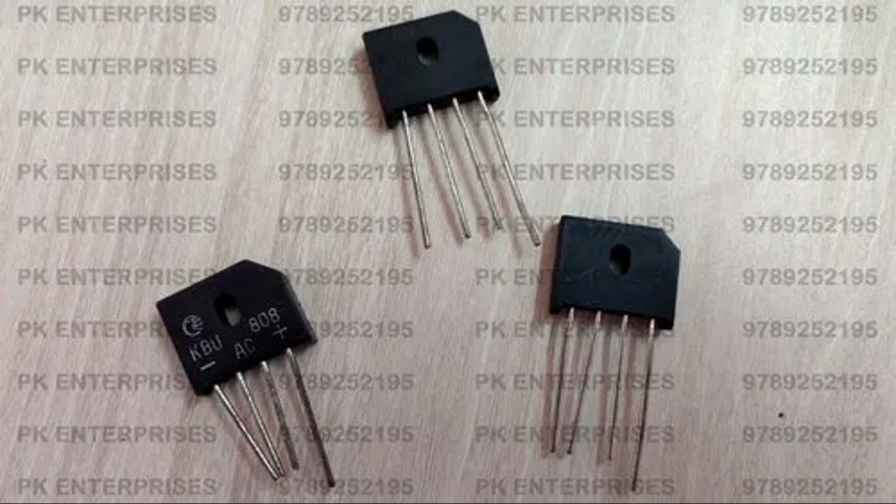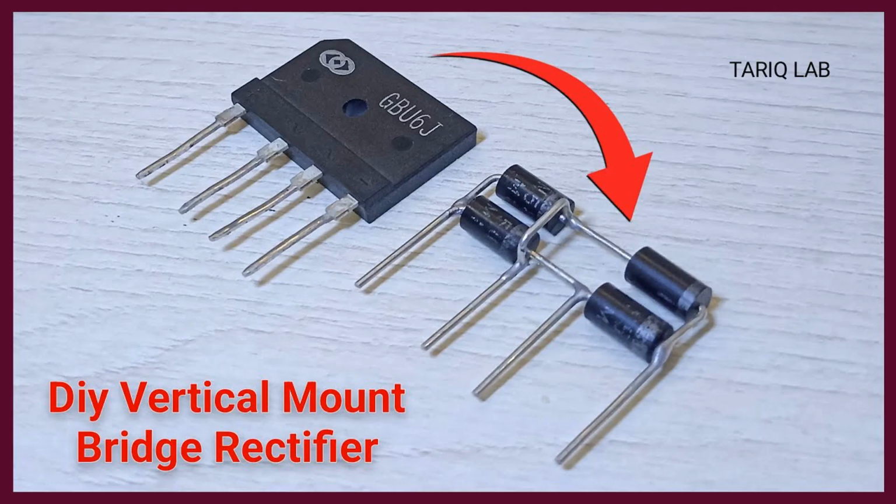Full-wave rectification. Bridge rectifiers provide full-wave rectification, ensuring that both the positive and negative halves of the AC waveform are converted into DC. This results in a smoother and more efficient power supply compared to half-wave rectification. Variable speed control. Many motor drive systems require variable speed control of the motor. Bridge rectifiers, along with associated control circuitry such as pulse width modulation, PWM, controllers, enable precise control of the DC voltage supplied to the motor, thus controlling its speed.